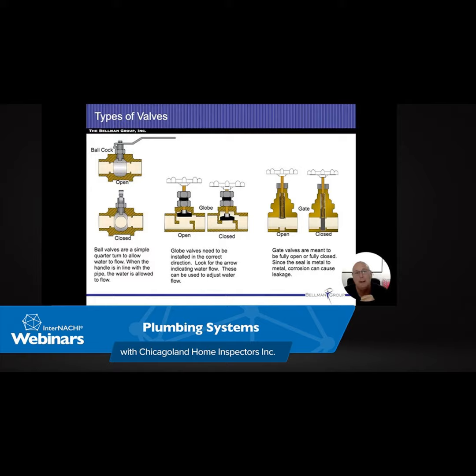Galvanized pipes pretty much have a lifespan of about 60 years, and it's been roughly 70 years since we started putting these things in. Now, there are a lot of people that will still replace with galvanized pipe. So it still gets removed and put back in.